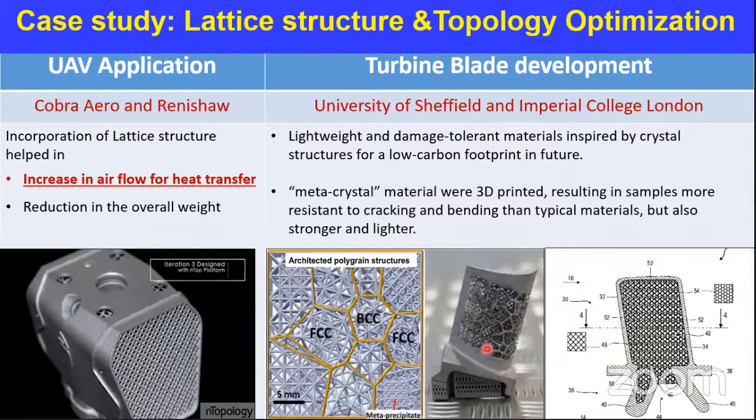So that is possible. And there are, of course, techniques like, you might have come across, thermal barrier coatings on the AM printed part itself. They can in fact take care of that thermal loading which comes onto the turbine blade surface. So it can be a coupled approach. If you have the AM printed turbine blade and then you do a conventional surface engineering technique like thermal barrier coatings, it can be a double advantage.